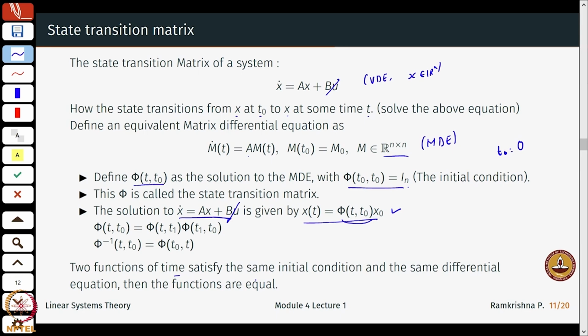And what is a little key here, which is not explicitly discussed when we do our basic state space representation in control 1, is that solutions to a given differential equation exist and they are unique. Essentially it means given an initial condition, I can only travel in one particular direction. There will be only one solution, or that I stand here and I can go this way, up, down, all those are not allowed, right.